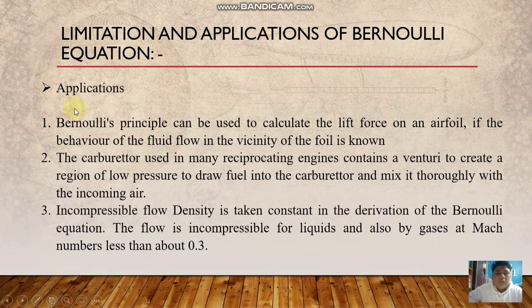Next are applications of the Bernoulli equation. Bernoulli's principle can be used to calculate the lift force on an airfoil if the behavior of the fluid flow in the vicinity of the foil is known. Next is the carburetor used in many reciprocating engines, which contains a venturi to create a region of low pressure to draw fuel into the carburetor and mix it thoroughly with the incoming air.